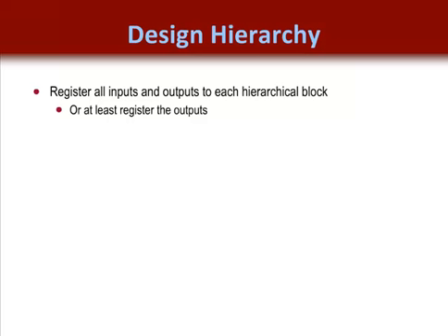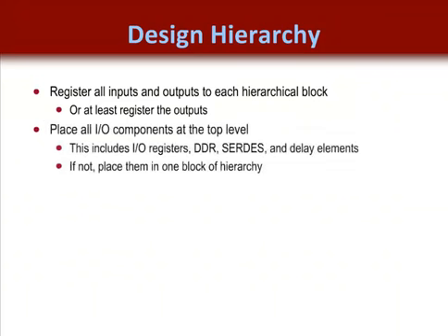In general, these practices are popular and worthwhile, but for them to be effective in meeting system performance needs, designers have to anticipate having signals travel a significant distance across the die. To help this, we recommend registering all inputs and outputs to your most critical hierarchical blocks. Likewise, you should try to keep your I/O resources at the top level of your design. Usually this is done through direct instantiation.